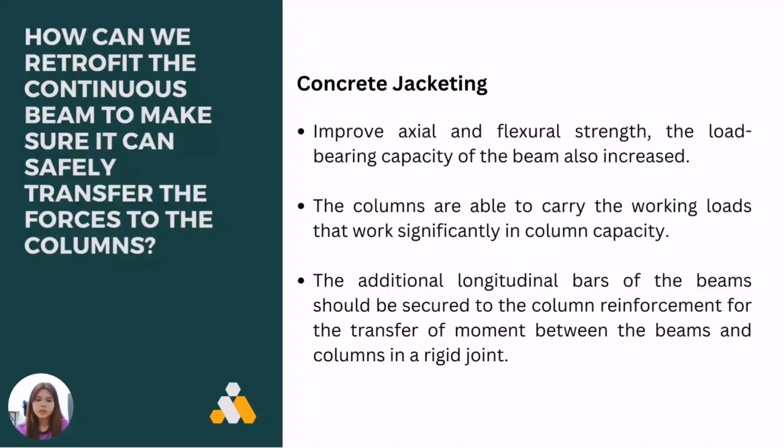Next, the concrete jacketing can improve axial and flexural strength in the beam. Also, the load-bearing capacity of the beam will increase. Therefore, the structure is capable of carrying axial loads and bending moments.